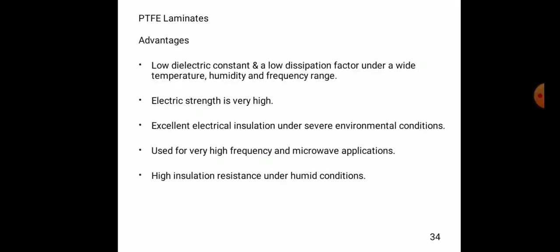low dielectric constant and a low dissipation factor under a wide temperature, humidity and frequency range. Electric strength is very high. Excellent electrical insulation under severe environmental conditions. Used for very high frequency and microwave applications.